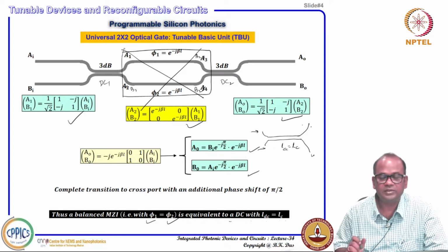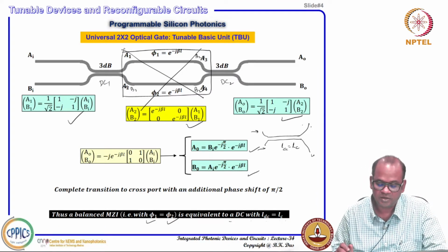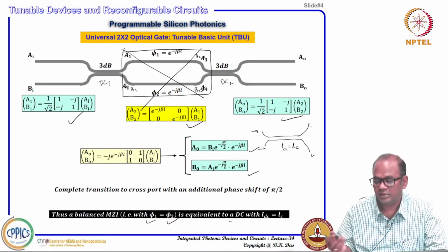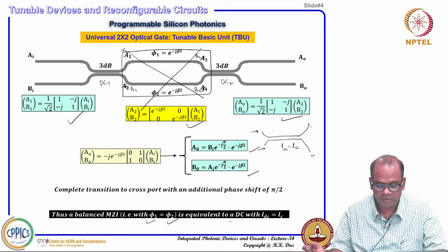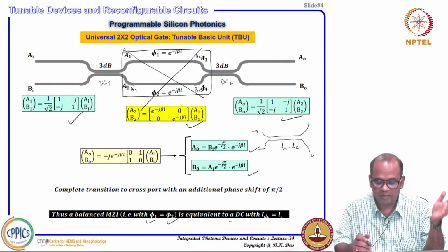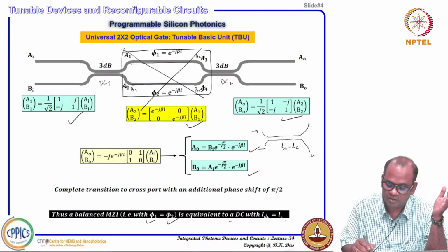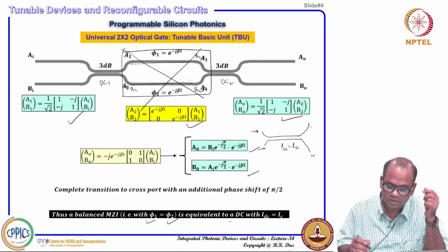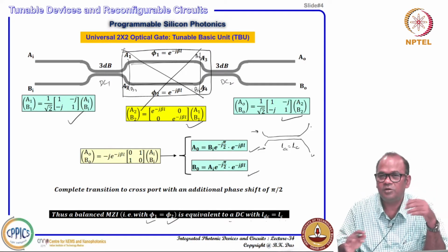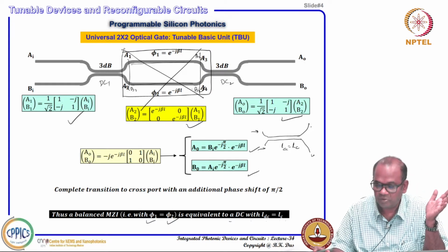So, if you operate this type of balanced Mach-Zehnder interferometer passively, it is actually nothing but a simple directional coupler. Instead of two directional couplers cascaded with a distance, with a certain waveguide in between, as if you can think that that is missing. If that is missing also, from a functionality point of view, no difference.